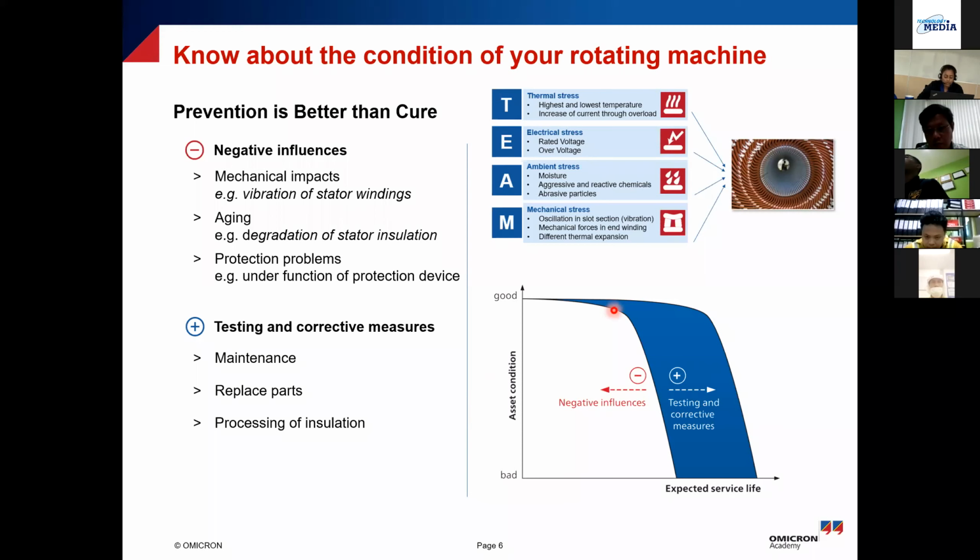Then during the service life, there will be a fairly constant failure rate. And when I say fairly constant, it doesn't mean that it's just stable. There can be some random faults. Like, for example, I had a failure where a worm entered into the switchgear. So that's a very random fault. And that is very much dependent on the maintenance. So you cannot say that that increases your fault rate, because that's something that we could have avoided. So there is a random failure rate, but it's fairly constant.